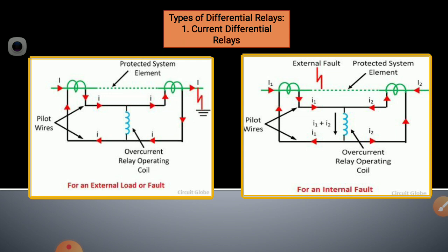Therefore, it is not necessary that the fault current flows to the fault from both sides to cause the secondary current to flow to the differential relay. So, flow on one side only, or even some current flowing out of one side, while a larger current entering the other side, will cause a differential current to flow to the relay operating coil.